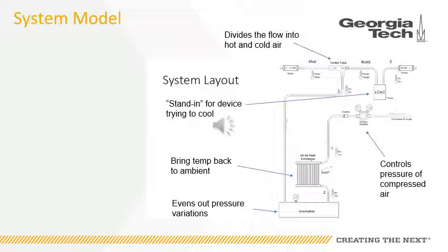The block is insulated, though some heat transfer will still occur due to the differential between the ambient temperature and the temperature of the block. The output of the block measures the temperature and pressure of the air just before it is vented to the ambient. The pressure at this sensor, marked as number 5, is at atmospheric pressure, though its temperature will be lower due to the cooling effect of the block.